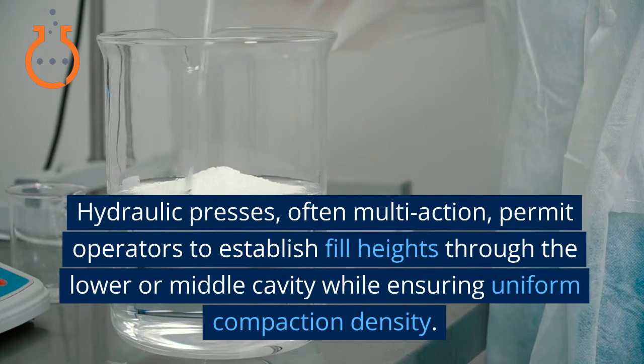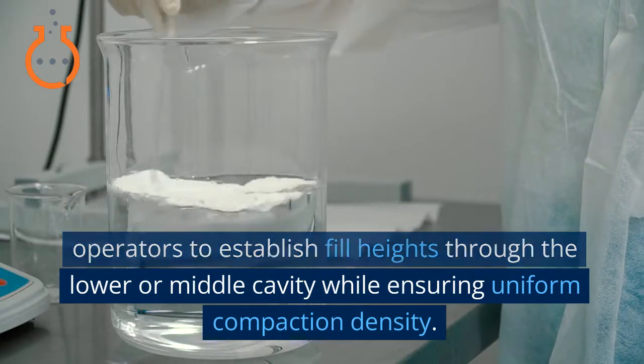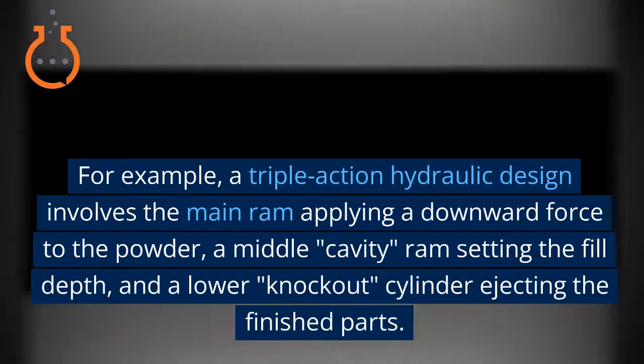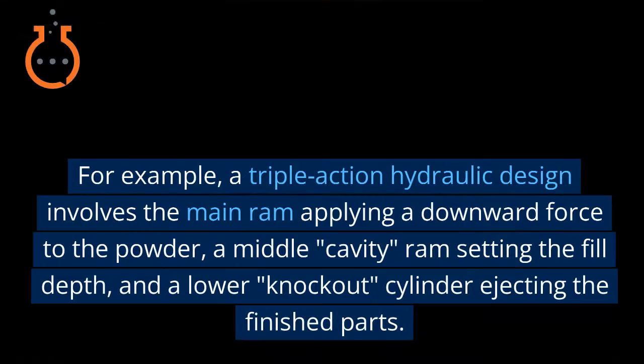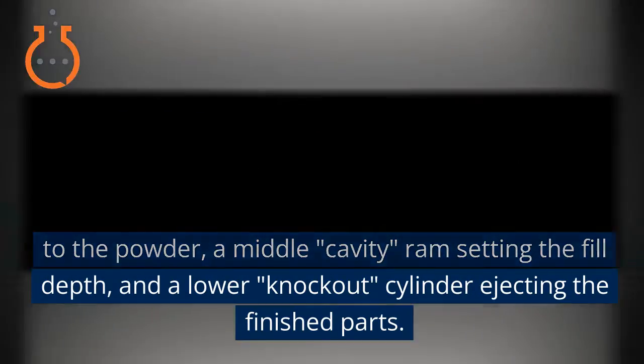Hydraulic presses, often multi-action, permit operators to establish fill heights through the lower or middle cavity while ensuring uniform compaction density. For example, a triple-action hydraulic design involves the main ram applying a downward force to the powder, a middle cavity ram setting the fill depth, and a lower knockout cylinder ejecting the finished parts.